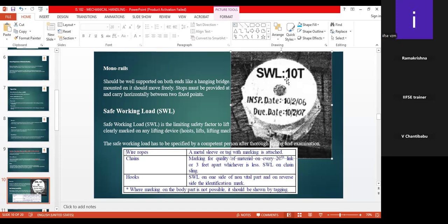Sometimes, especially for pressure gauges, the gauge is 0 to 50 bar, but they calibrate a range of 50 to 200 bar. If the pressure gauge range is 0 to 50 bar, they have to do the calibration for the same. They should not do a range of 0 to 100, or 10 to 50, or 0 to 200, or 150. They have to calibrate the same range.